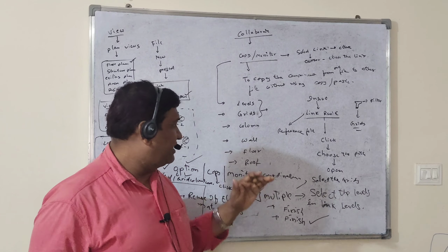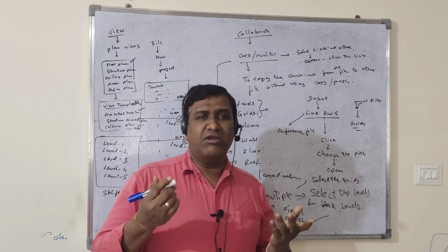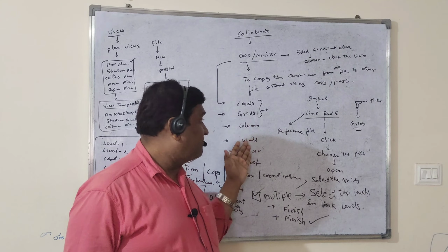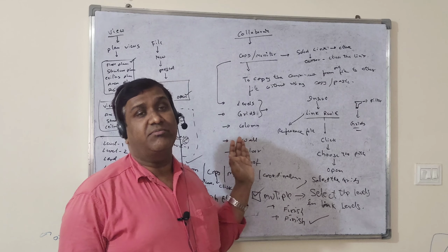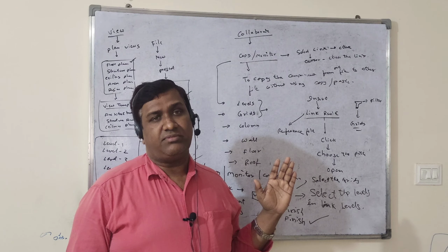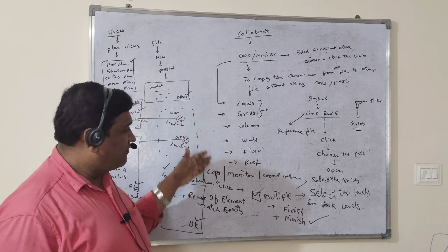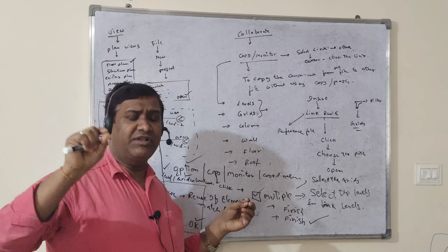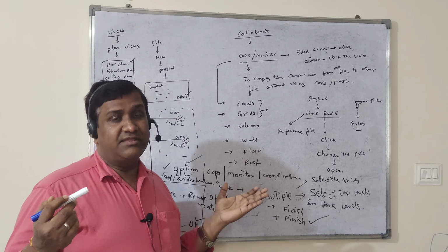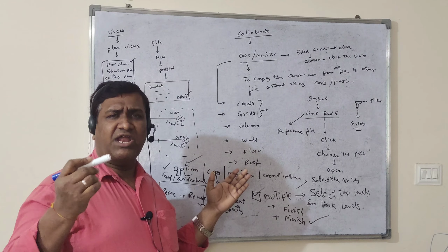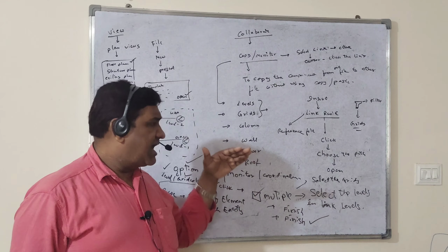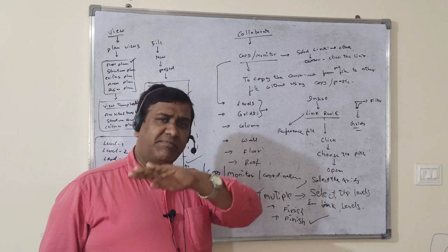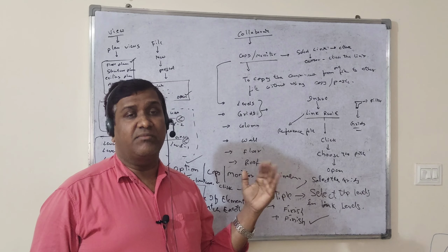But architecture people will never do columns and walls copy monitor, because they already have their model. Why would they do it? It is not required. So that's the reason the MEP team uses copy monitor more often, because they require it. With the help of this copy monitor they work further, because it takes less time. If you create them manually, it will take a lot of time. With copy monitor, within a fraction of a minute you get all the levels and grids, and whatever the naming or alphabetical letters in the reference file, the same comes as a carbon copy.